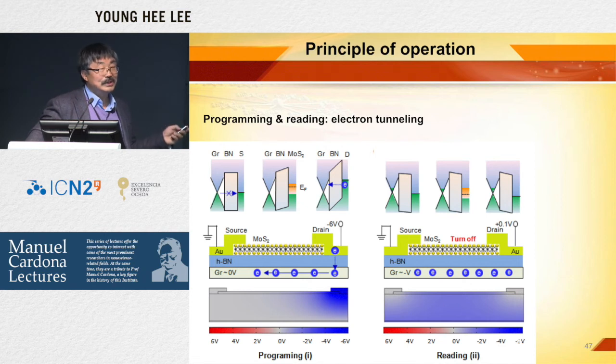We actually analyze all this using this capacitance coupling. And here there's no potential drop. So basically, the electrons tunnel through this one is accumulated in the graphene. And then you can actually use a small voltage to control the source and drain current. This one acts as a charge blocker. So if you have an electron coming, in this case, when you have charge, then the current is very low, right? But the hole current flows more dominantly. So actually, this is possible.